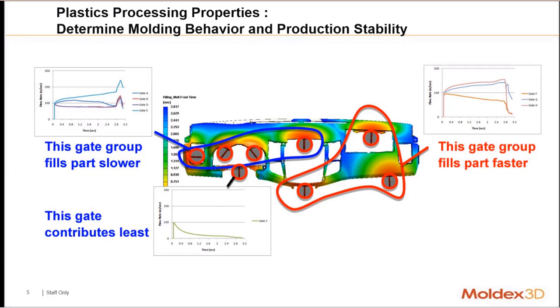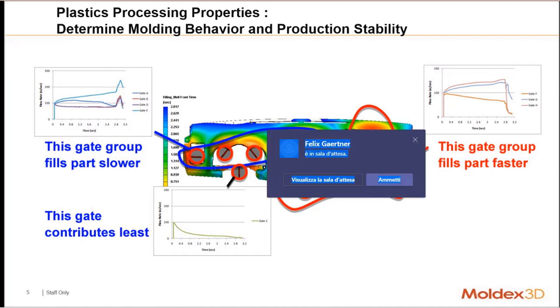So usually in the product design workflow, we choose the material based on its mechanical properties. Then we design our mold and specify our process conditions, which can improve the moldability or the processing window of the selected mold and material.